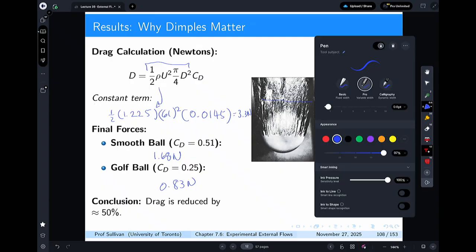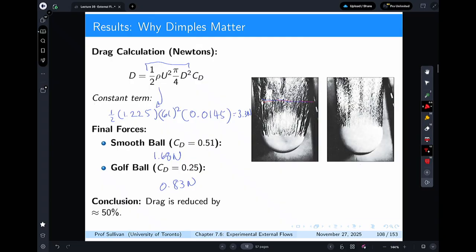Hold on. So this is actually a really good image to work with. If you were doing a control volume on that, everything that's in the disturbed zone is low velocity. And so you know that with low velocity you have high pressure, and that high pressure is acting on the control volume. On the front side of that sphere, on that ball, you have low or the same velocity, so the same pressure in all of these cases.